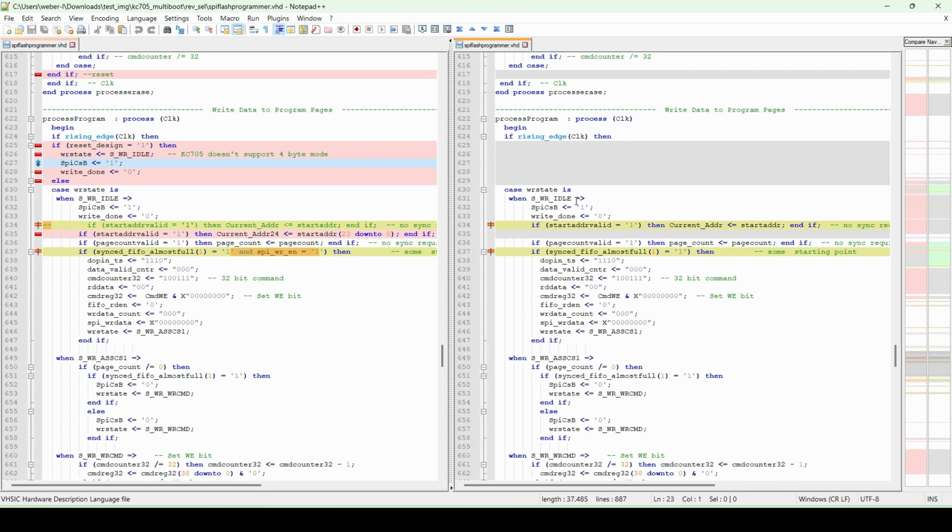This SPI write feature is only triggered by the FIFO full. In any case, the FIFO is not ready and glitches with the full signal. The SPI write actually writes some 0 bytes to the warm boot sector, which is very dangerous.